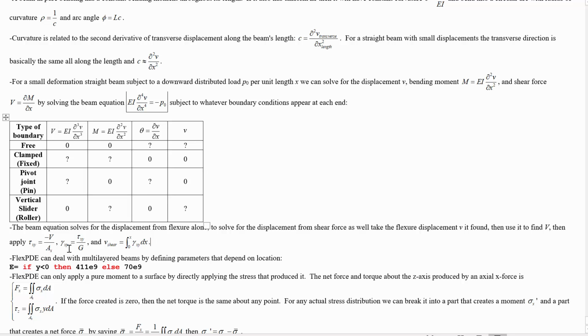that break this, especially if you end up with a setup where there's a lot of y in the x direction shear strain. This is assuming that that is 0 in order to say that all of gamma xy is manifested by shear strain on the x face in the y direction. So that's one big approximation that comes from using this to then calculate the total displacement, right?